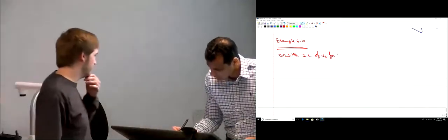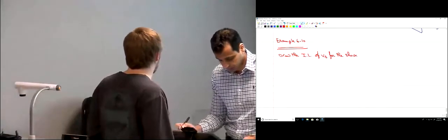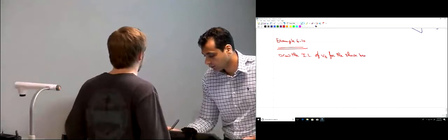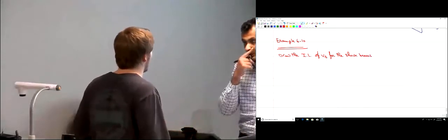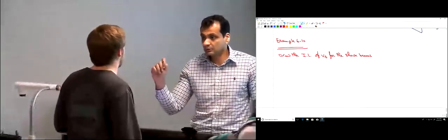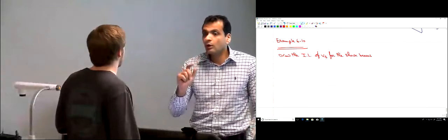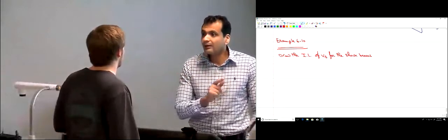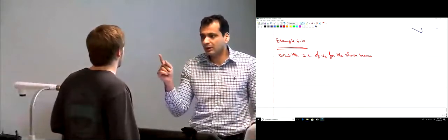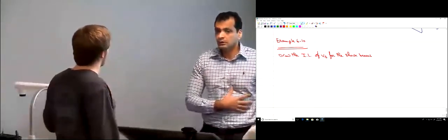Dr. Ragab, I had a question about the project that's been bugging me. Are we supposed to include the dead load, I guess the weight of the beams? Okay, you do one of two things. You either calculate the own weight of the beams yourself and add it, and make the self-weight multiplier 0. Or you can leave it and put the self-weight multiplier. Both are correct. 1 or negative 1?